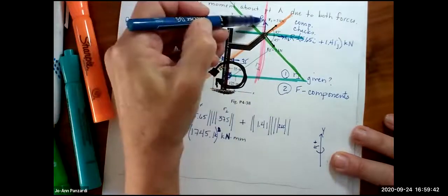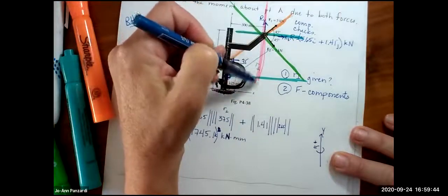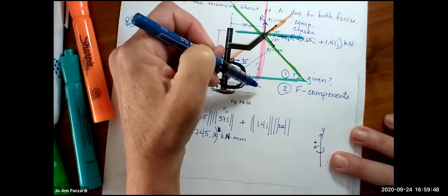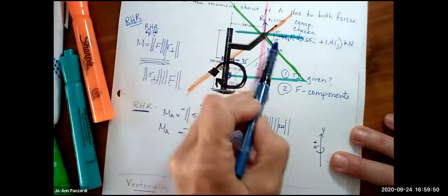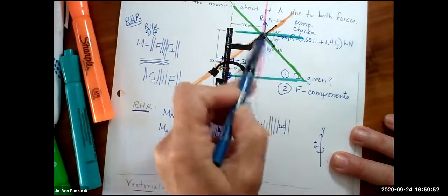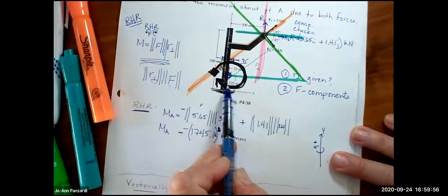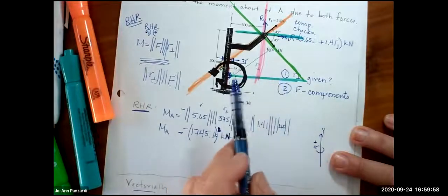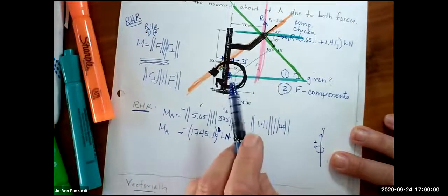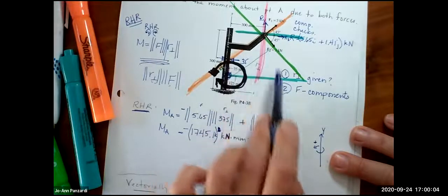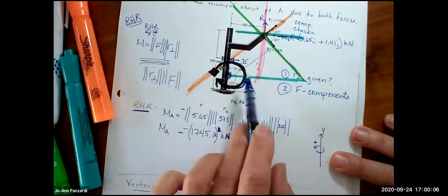And the resultant y is intersecting the x-axis. It cannot create a moment. There's no lever arm. So a force in the x and y can only create this moment. When we get to 3D, which we are in a little bit, let's wait until then, and then we can talk more about where the moments are being created. Okay, Jason, what's your second question?